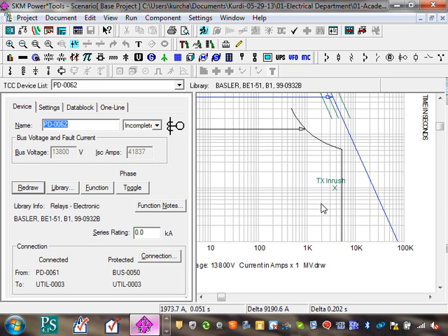So the wire gets hot instantly, it acts like a heating element. It starts melting the insulation, and after it melts the insulation, it catches fire. Of course, you're in a conduit, but then your circuit breaker will trip. You have to replace all your cables. Is that why you have a circuit breaker, though? So when you're designing this, you have to specify how you're going to set your circuit breakers before you know what size wire you're going to pull. That's what your short circuit analysis is.